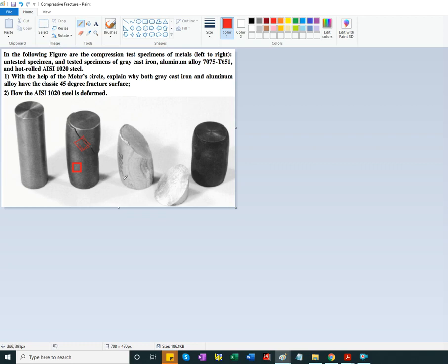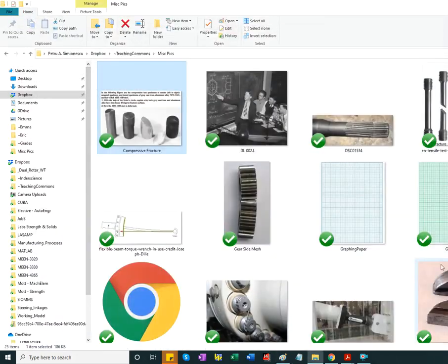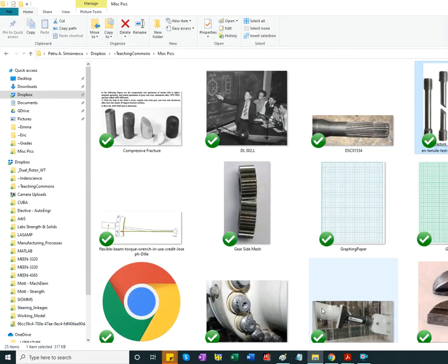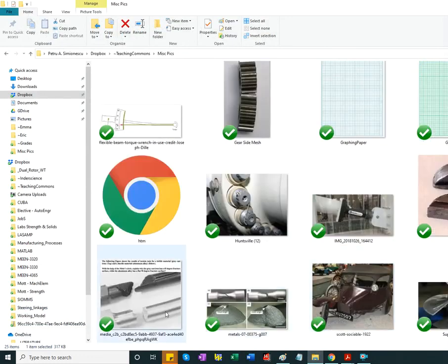Or if there is a repair, there was a fracture and it was welded, and you want to know what would be the stresses parallel and perpendicular to the repair. And other examples of this: this will be ductile tensile fracture. This is brittle compressive fracture, and not all brittle materials fracture this way at 45 degrees. Really, there are others that have different behavior.